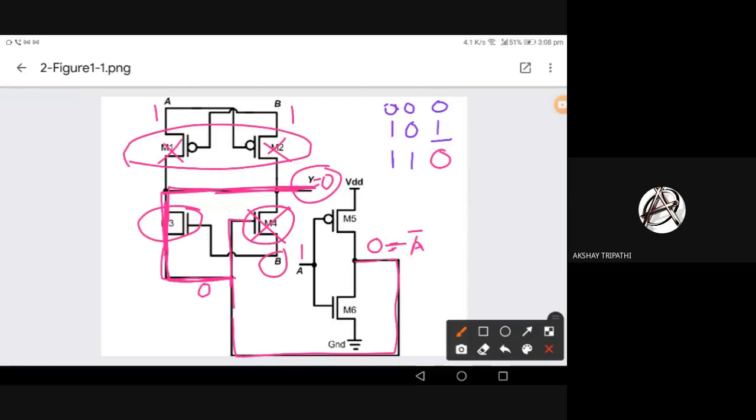So if you understand, this field is digital VLSI design, where circuit designers, electronics engineers, and VLSI engineers are designing different kinds of gates, chips, or even processor parts. Basically, all microprocessors, RAM, or digital things are comprised of different types of individual gates: NOT gate, AND gate, OR gate. The fundamental gates are the NAND gate and NOR gate, right? And the NOT gate. Because using NAND gate and NOR gate, you can make all other gates.